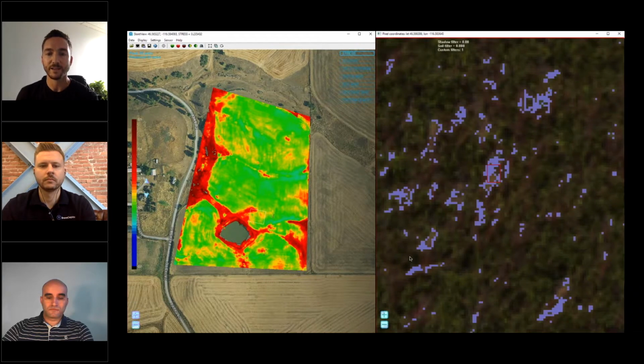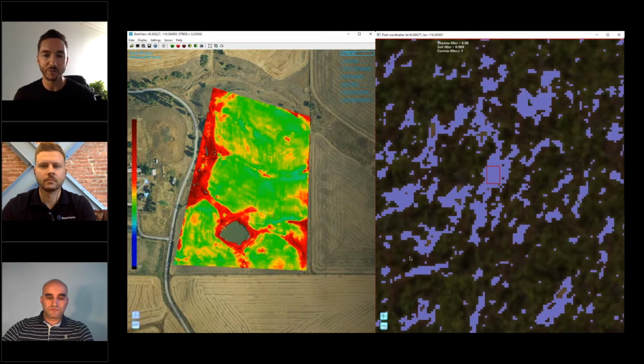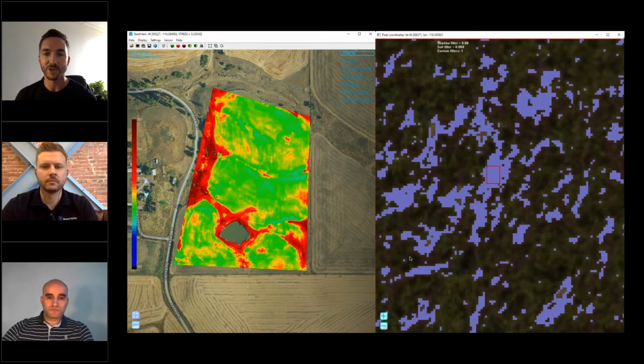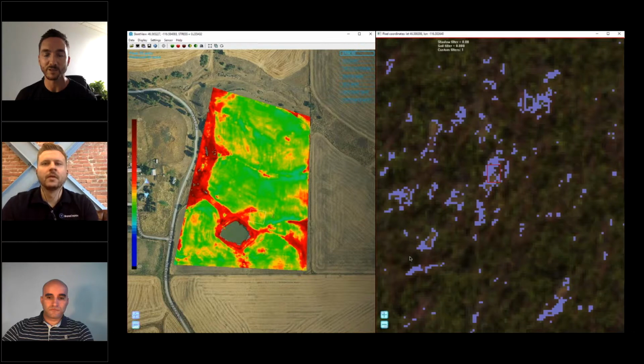We'll highlight any pixels that have that same spectral signature, and you can adjust the sensitivity of that filter. Just by scrolling the mouse wheel, you can say, put some broader bounds around that match and show me what that looks like. Show me a very tight match for that spectral signature. And you can visibly tune that filter to say, okay, yeah, it's grabbing most of those pixels that I can see here with my eye.